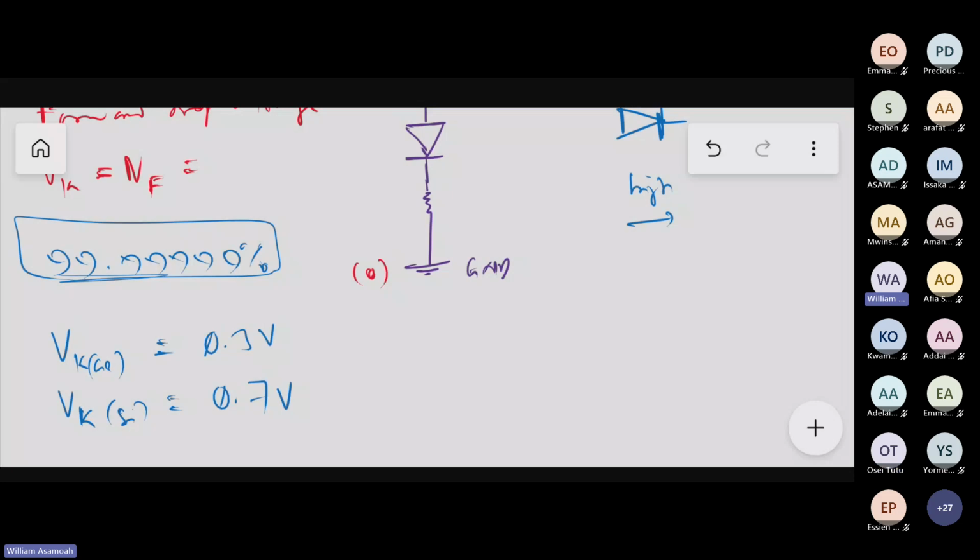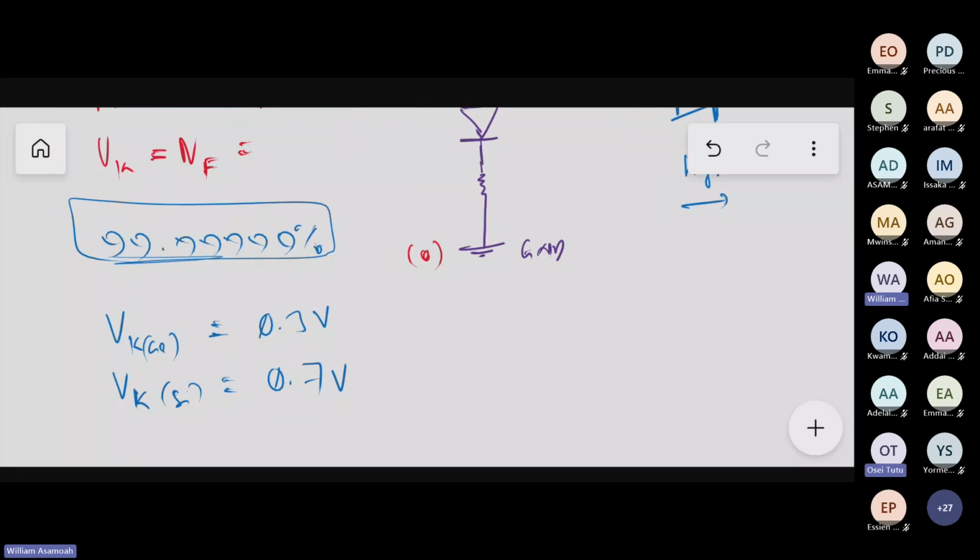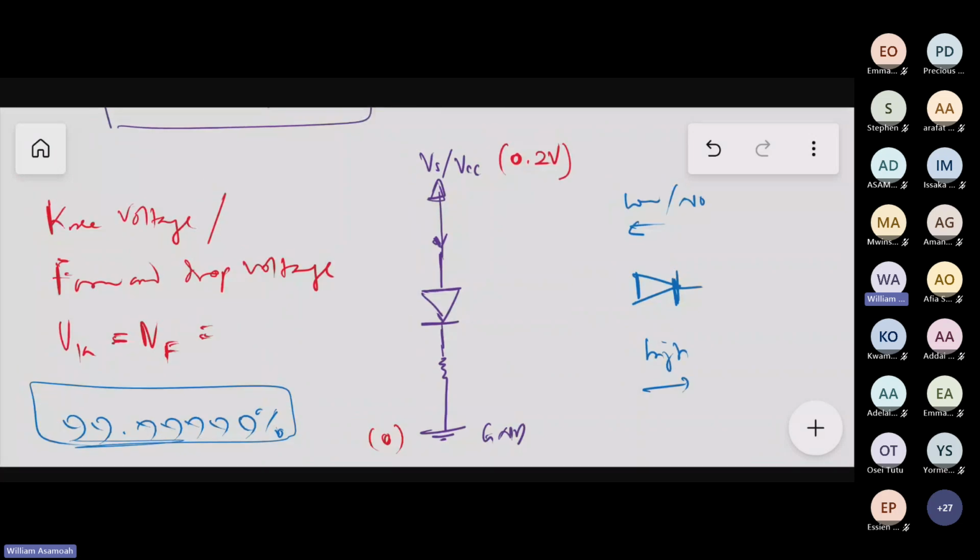So it needs a voltage of 4.8. Meanwhile, when you were designing the system, you provided only 5 volts. So the moment temperature rose beyond what it can tolerate, the device that was working well at 5 volts will now burn at 5 volts because temperature has risen. So germanium was that noisy, and we didn't really like germanium, right? So we had to research.